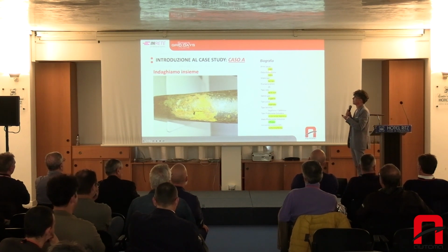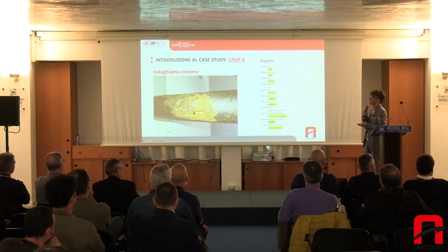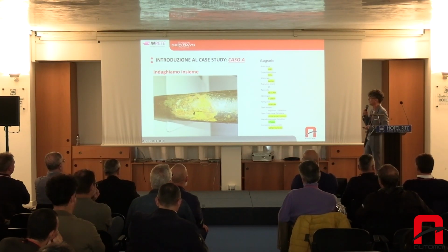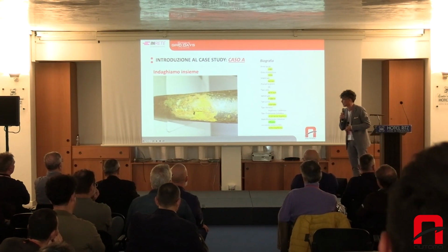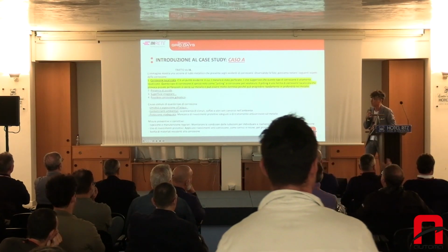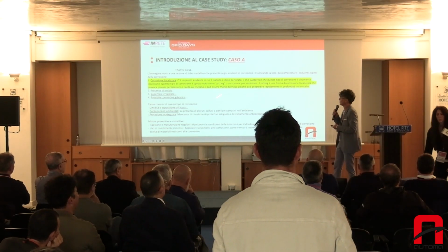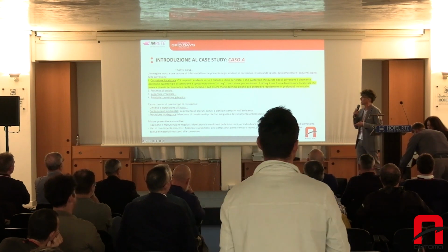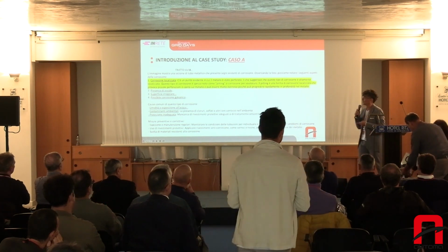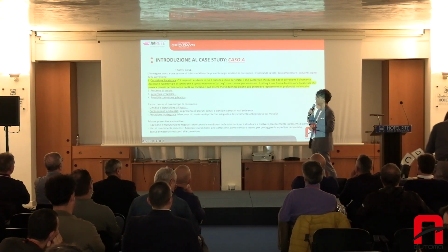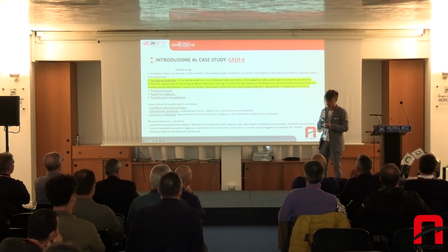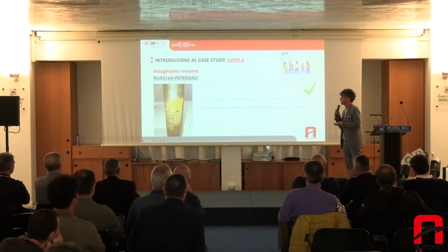So this is a pipe of 1985, which was no longer used in 2024. That's in steel, medium pressure network, earthed laying, impressed current in a system of cathodic protection with no interferences. So I took this picture and I interrogated ChatGPT, and that told me that basically it is localized corrosion. It's evident that the metal was pierced, and this is basically the information given by artificial intelligence.